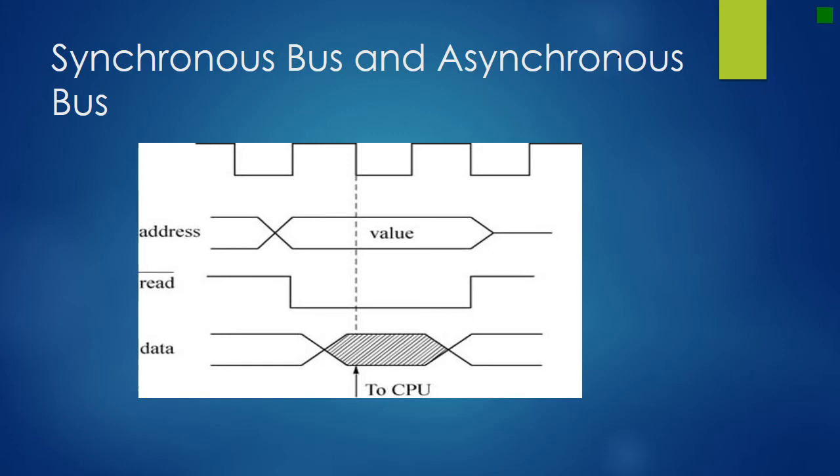When the CPU wants to read data from memory, the address signals are first enabled and then the read command is issued. The data will not be read until the next clock edge is reached, so that the time of the read action has taken place. So all data are already stored in the memory data register and in stable conditions.